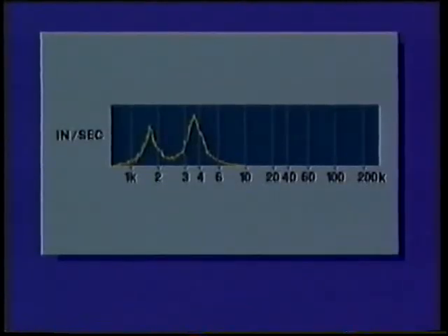This vibration signature was taken on a bearing with a loose housing. The machine RPM is 1800. As you can see, there are 2 amplitude peaks. One occurs at 1800 CPM, or 1 times RPM. The other peak amplitude occurs at 3600 CPM, or 2 times RPM.